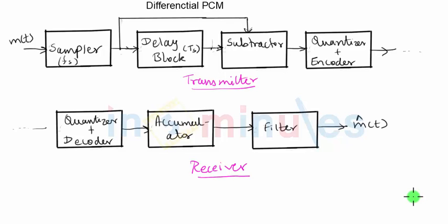If you remember, in pulse code modulation, we basically send the signal through two important processes. The first one is called the sampling process and the second is quantization. Sampling gives us the discretization of the time variable in the signal, and quantization gives us discretization of the amplitude variable. Only when both the independent time variable and the dependent amplitude variable are discretized can we achieve a perfectly digital signal, which is written in the form of ones and zeros.